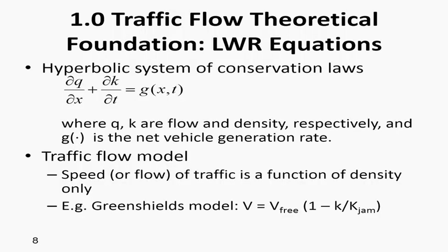Before I move into any detailed traffic flow simulation package, I would like to take about 10 minutes or 20 minutes to introduce the traffic theoretical foundation, LWR equations. Typically, the traffic flow can be viewed as a traffic flow stream governed by a number of important equations, such as this flow balance constraint. We have this set of partial differential equations. And we also need to have the traffic speed-flow-density relationship, such as the Greenshields model.